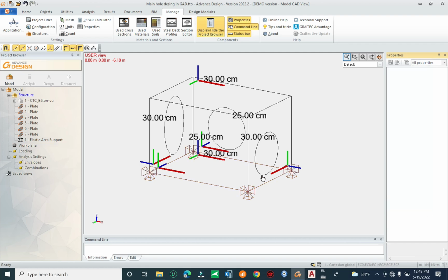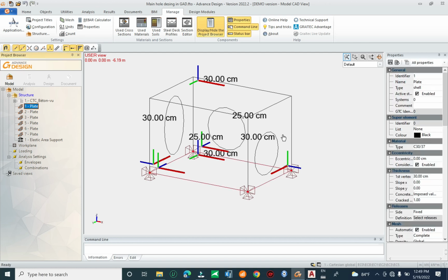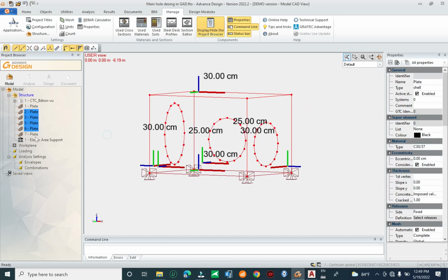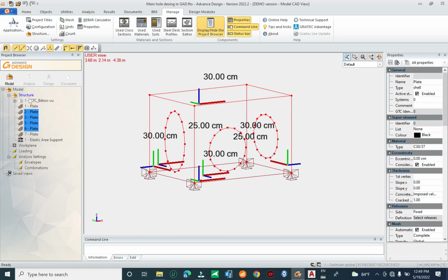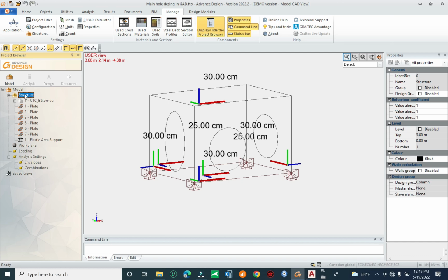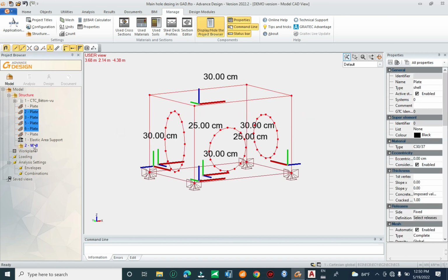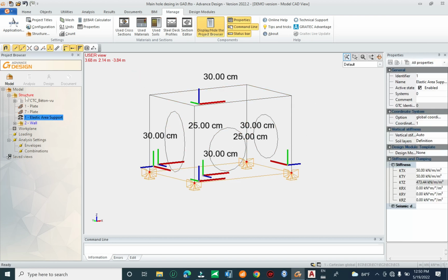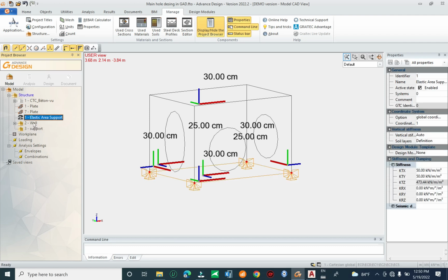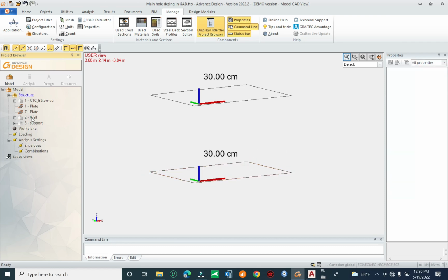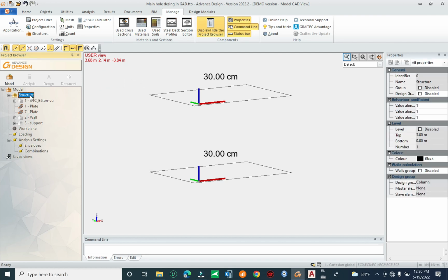After completing, you can create this frame for the wall, the top and the bottom, each one. Now press Escape. I call it wall and select all walls, click to the wall. Escape again, support, and click on support, turn off support, turn off wall, and Escape again.